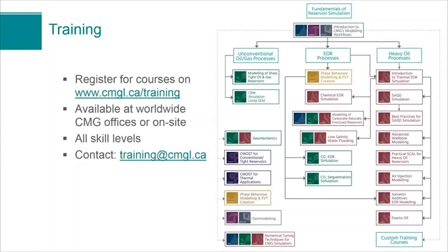I think we have time just for one more question, and the question is from Khalid, and the question is, can we model shear impact on viscosity at well completion level, for example across ICDs or FCDs? Yes, we can in STARS if you use our FlexWell feature to actually model the flow inside the well.